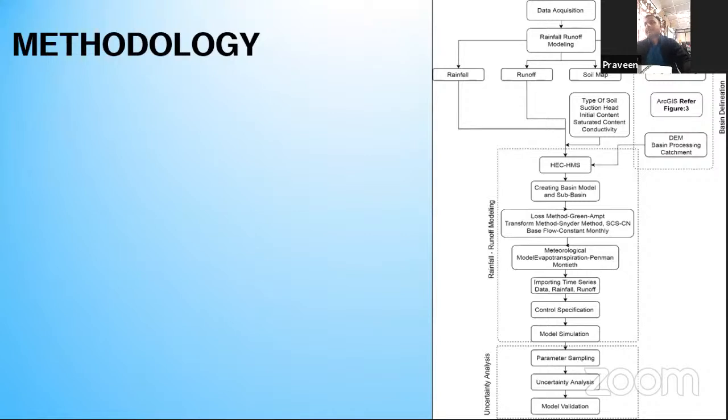Suppose you consider the soil parameters. There you have the input of the infiltration rate, the initial water content, the saturation content, the conductivity. Plus there are so many other parameters, like lag parameters, like the basin lag parameter, which will also govern the relationship matching, fitting the rainfall and the discharge.